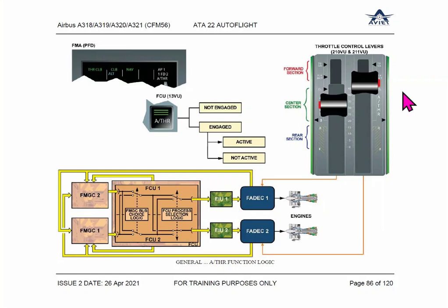So, sir, is it correct to say that only during a TOGA requirement it will supersede the lever selection? If the FMGC signals auto thrust, high angle of attack condition, alpha floor or high angle of attack, whatever you call it, it will supersede the lever position. And that is automatic, not manual. All right. Okay. Thank you.